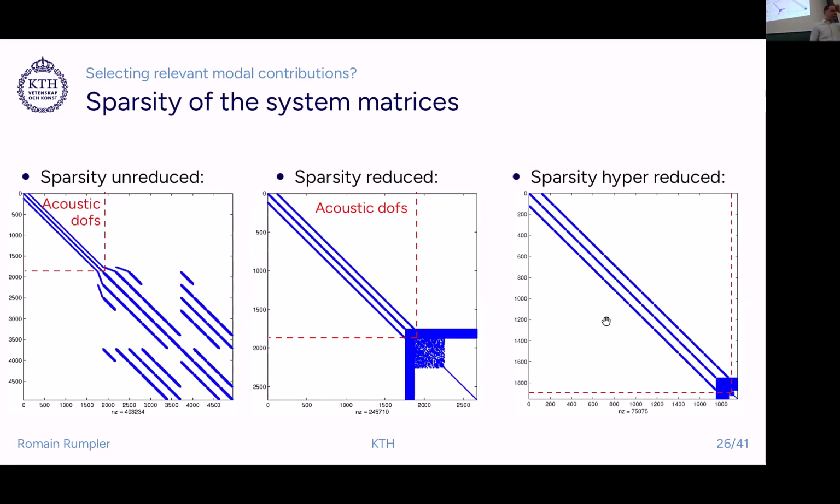You remember this question that we use the modes based on this low frequency stiffness and this mass matrix alone. There's no guarantee that this will lead to a good result. There's no orthogonality property that is a priori known for the middle matrices there. But we can just have a check, looking at the projection of those middle matrices on this modal basis. What is the sparsity? Do you have diagonal, piecewise diagonal, sparsely populated or fully populated middle matrices? Well, this is the kind of sparsity analysis that we can do.